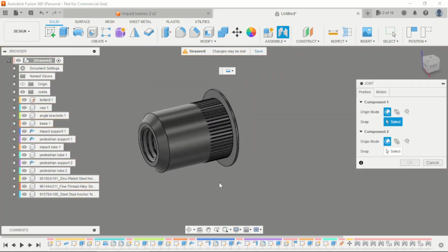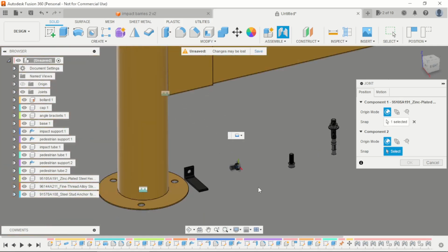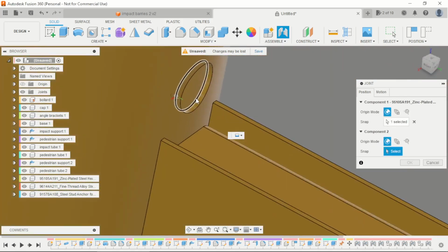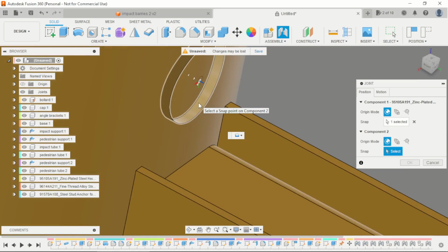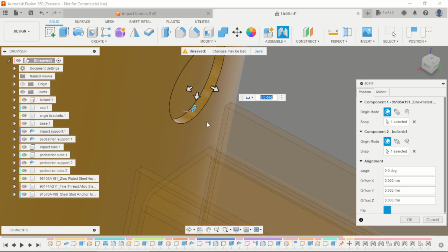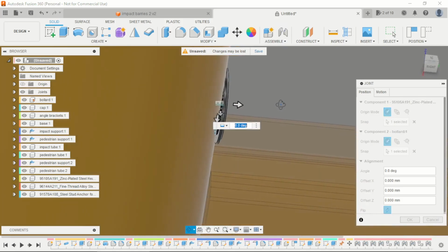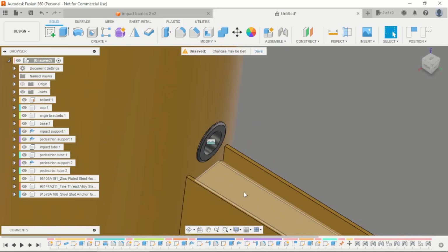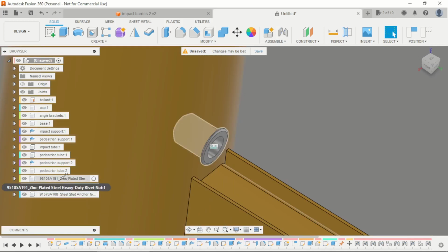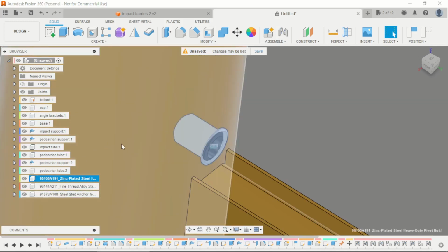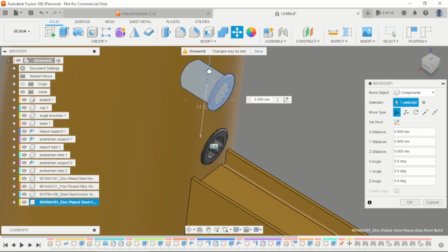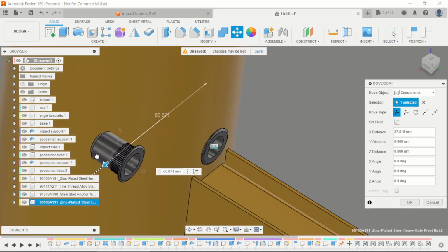Now I can joint, select the face, hold the Ctrl, click on the center point. On this, choose the first option here, not this in the center or deck, this first. The component will be here. Select the component, Ctrl C, Ctrl V, here and here.